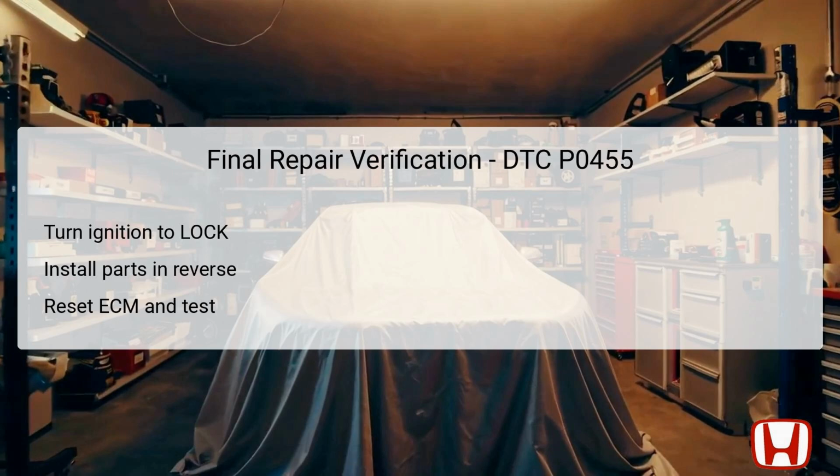Reset the engine control module (ECM) using the Honda Diagnostic System (HDS) to clear any previously logged DTCs. Finally, perform the EVAP function test to ensure that the system is operating as expected with no new codes emerging. Confirm success by ensuring the test results return satisfactory outcomes.